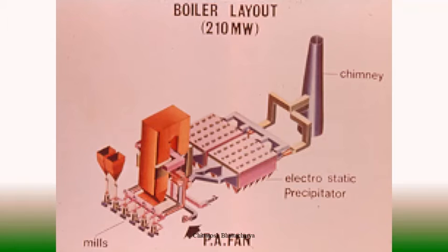So naturally if coal is being ground and supplied with primary air to pneumatically convey the coal to the furnace, there is every chance that coal dust generated within the mill may ingress into the vertical shaft or the gearbox through which the prime mover is running the mill.